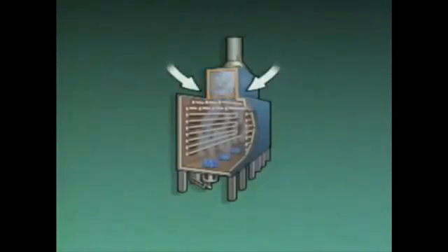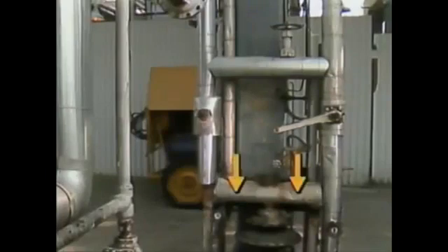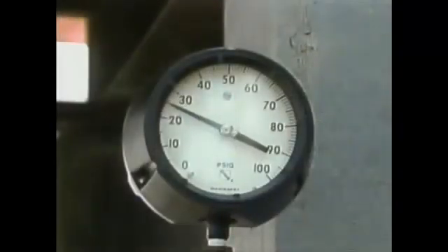Then if you've got air leaking into this section, it can combine with the unburned fuel and ignite, which could cause a lot of damage. If you have freeze-ups, you may find them in low points in the fuel system, where moisture can collect and freeze. With freeze-ups, the fuel header pressure may decrease since the ice restricts flow in the fuel line.